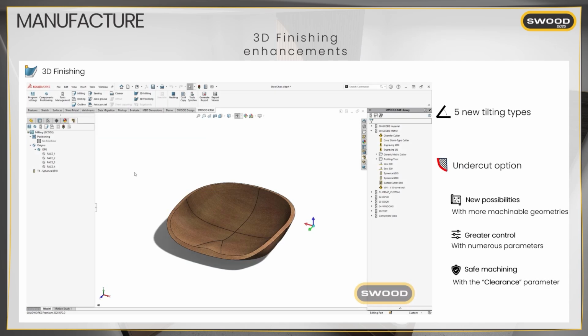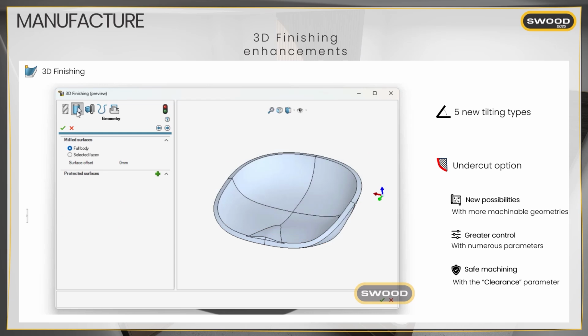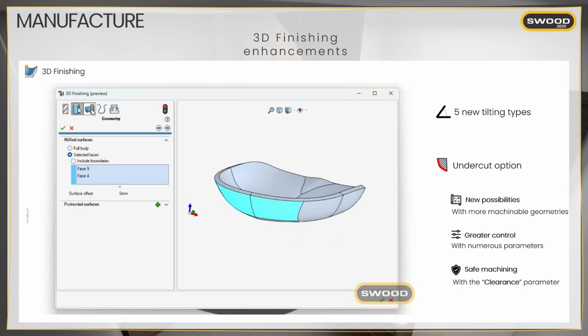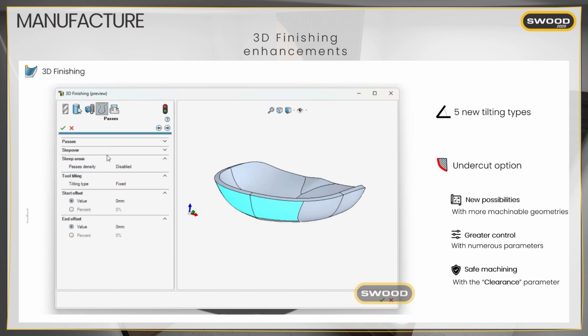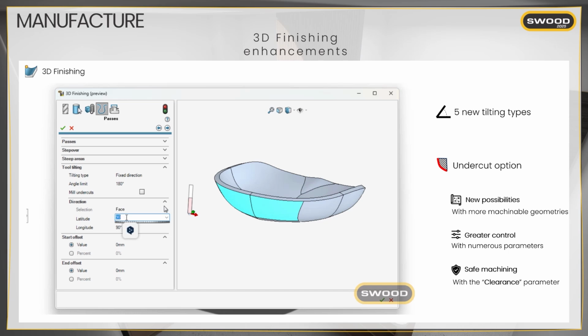So as before, here I'm going to create a new 3D finishing operation on this part. I'm clicking on the 3D finishing, selecting the surface I want to mill. Then I have access to all the parameters I want. If I want, for example, to set up the angle of the tool by using the new tilting types. And here, as you can see, it's not possible to cut from the top the surface I select. So by using the undercut option, I'm now able to mill it.